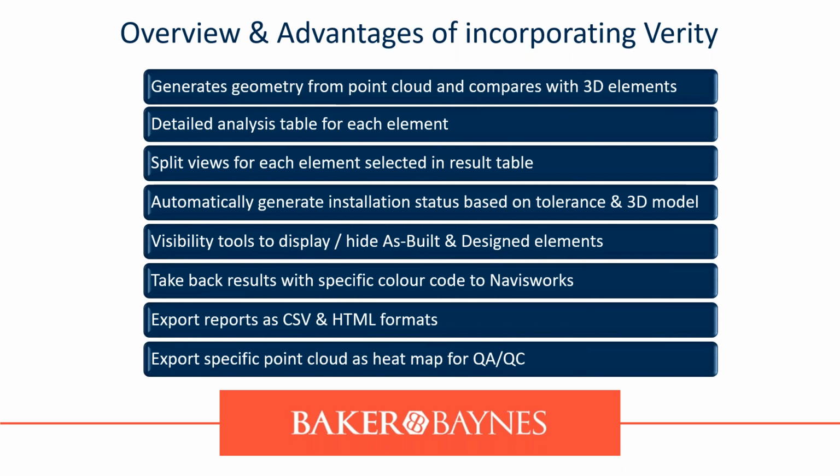But whatever I've just explained on the previous slide, it incorporates all of that, where you can combine the tolerances that you set on the point cloud versus your design model. You can update it to get a complete CAD model and use that for handover. You can even export element data to give a report to say that this is how it was constructed, and these are the tolerances, or the discrepancies between the point cloud and the actual building design, and it helps you negate problems in the future.